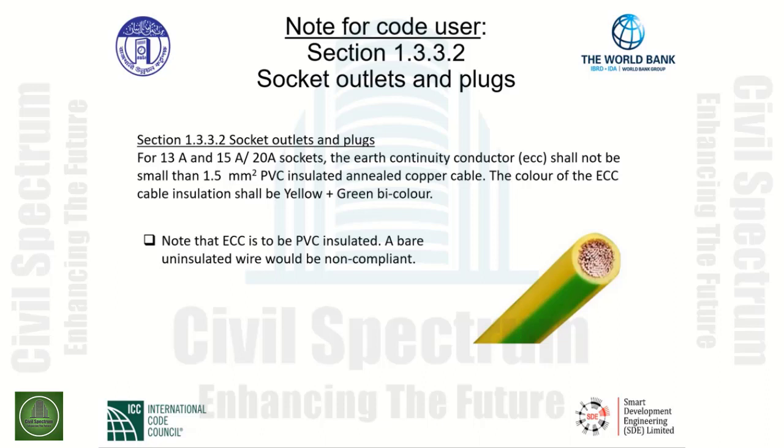Note that the ECC is to be PVC insulated. A bare wire would not be compliant with this section. As we could see in the picture, we have a PVC insulated conductor, and the outside color of the insulation is yellow with a green bicolor.